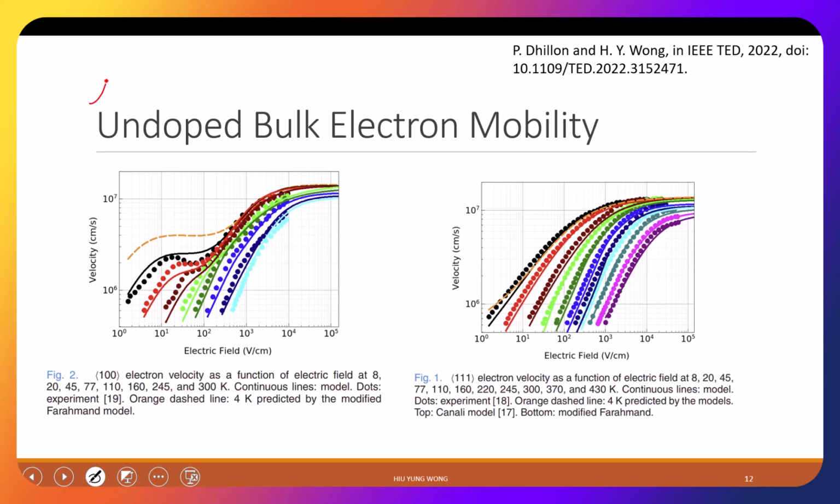Undoped, so what is the mu Coulomb? Very small. No, you trick me. Small in terms of what? No defect, no scattering. Very small scattering. But it means the Coulomb mobility is infinity. When it is bulk, what does it mean? It means I'm not transporting at the surface. It's just a crystal. So I don't have surface roughness scattering. So this mobility is purely just the phonon scattering.